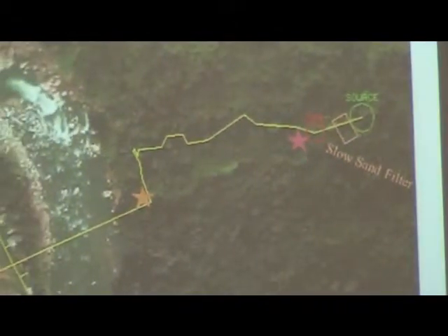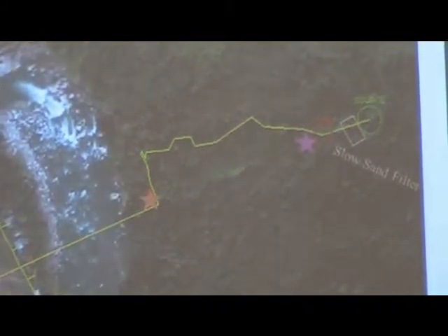This blue star represents a blow-off valve at the lowest point in the system to get rid of any potential sediment that accumulates. And this pink valve is a float valve placed right at the tank, which will shut off inflow from the source when the tank is full and turn it back on when the tank begins to deplete. This is so that we don't use more water than is necessary and have overflowing in the tank and wastewater.